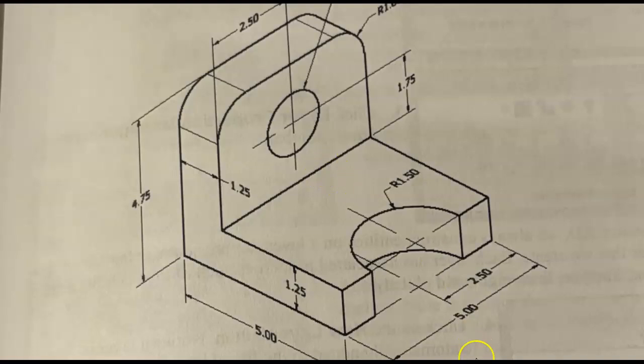Now, we can change to the ISO top, and we can start to draw from here in the ISO plane. We can go to the ISO plane right. We can start to draw in this area. So there are different ways to do this. We're going to go ahead and keep it in the ISO plane, but for right now, I am going to turn my grid off so that you can better see this, because I am going to copy some stuff over, and we're going to watch and see what difference it makes between the ISO plane left and the ISO plane top.